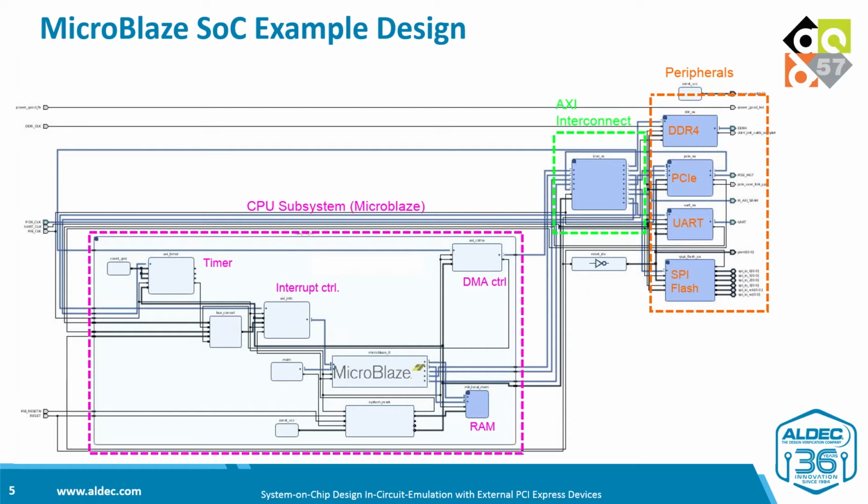The PCI Express device in our design is a root complex. That means our SoC can talk to other PCI Express endpoint devices, and the network interface card is one of the examples. The embedded Linux kernel can recognize the PCIe root complex controller, and further down the link it can enumerate and configure devices connected to the PCI Express bus.